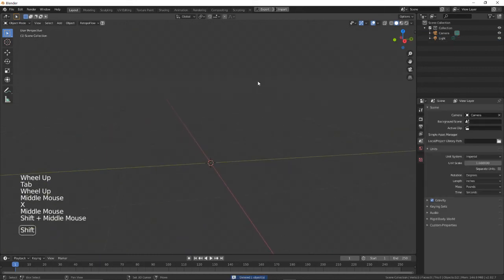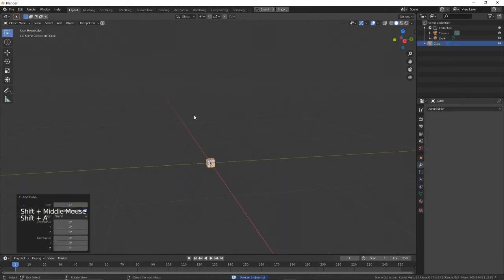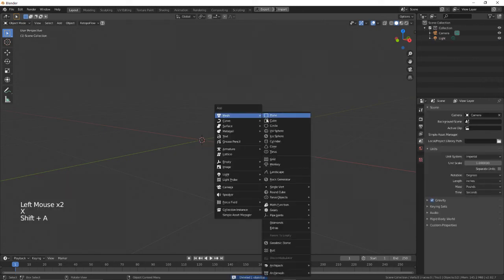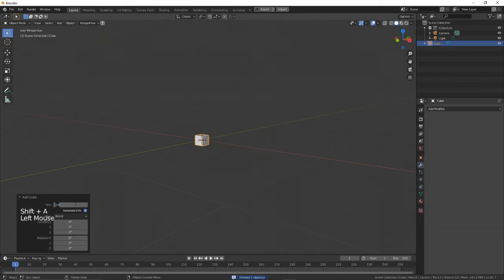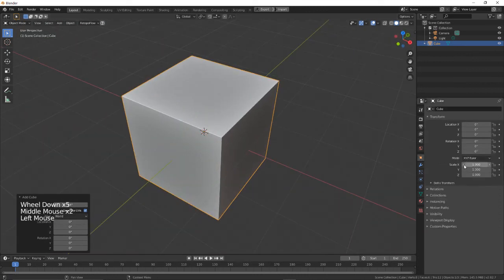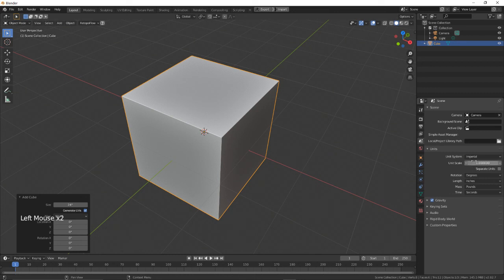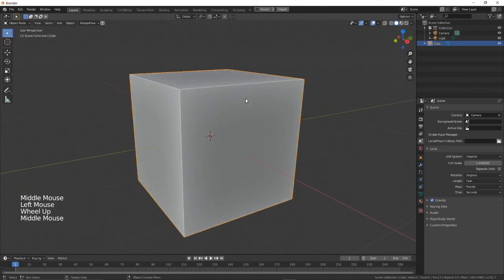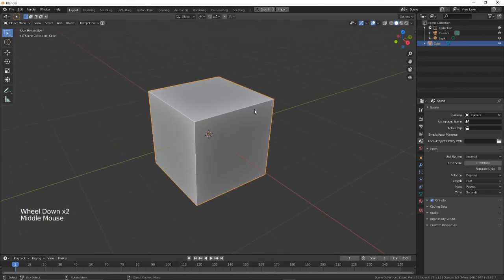All right, removing this weird looking object aside, I'm just going to go back and add a cube. Let me scale it. Let me add the cube and make sure that it's at, let's say, 2 feet. 2 feet. There we go, 24 inches. Feel free to change this in between whatever you find useful. So let me change that to feet. And I'm going to go over the basics of modifiers and then sculpt mode within the next video.